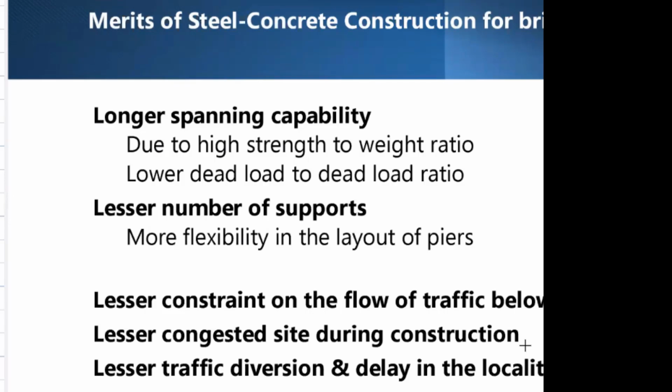For example, our experience is that only for the piling, we will block the site phase by phase. Once the pile cap is done, and if you use steel, it is a simple erection of the pier. We will remove everything and leave the space free for traffic. That's what we mean by less constrained on the flow of traffic, because everything is going on top. You can even do it at night.